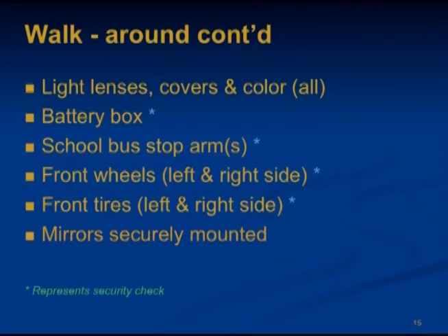School bus stop arms, make sure that they're secure, that they open and close easily, that there's no loose wires or nothing unusual. And the front wheels and wells, no excessive corrosion, cracks, or other damage. Make sure that the rims are not damaged and have no welding repairs. Make sure the lug nuts are tight and not missing. Hub oil seals are not leaking.